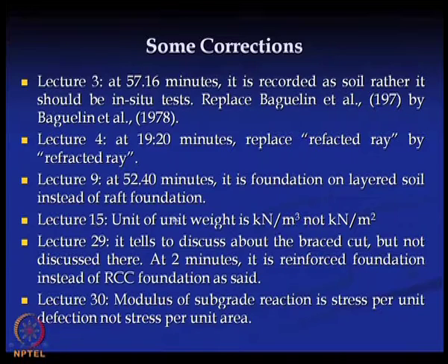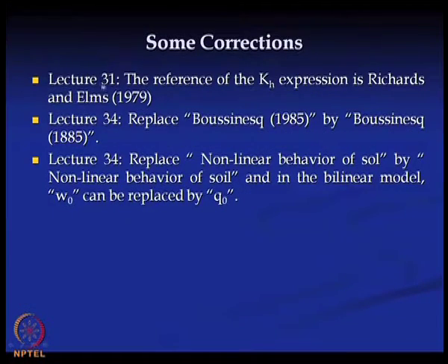In lecture 15, unit weight is kilonewton per meter cube, not kilonewton per meter square. In lecture 29, it says to discuss brace cut, but it is not discussed there. At 2 minutes, it is reinforced foundation instead of RCC foundation as said. In lecture 30, modulus of subgrade reaction is stress per unit deflection, not stress per unit area. In lecture 31, the reference of the KH expression is Richards and Elms 1979.